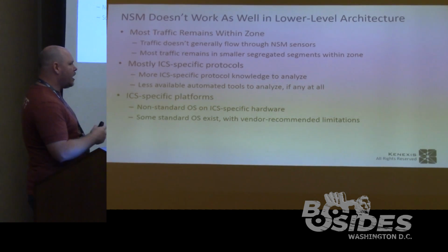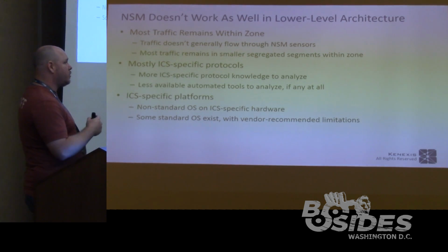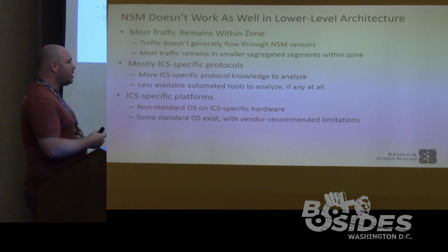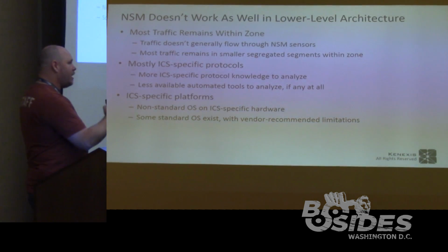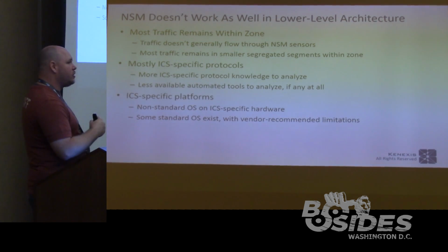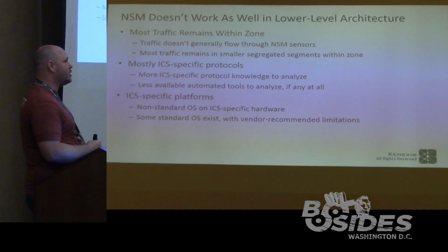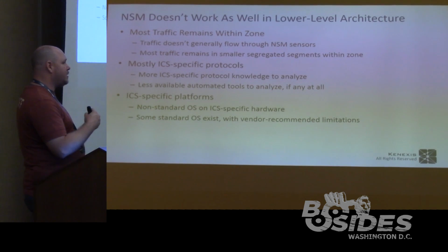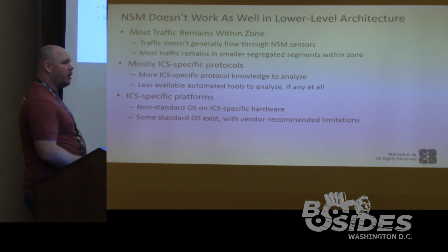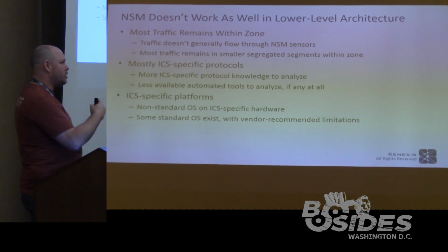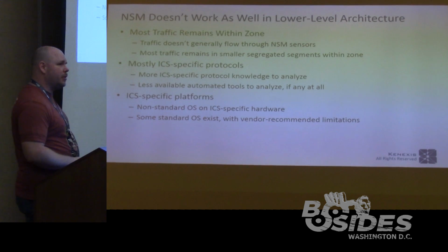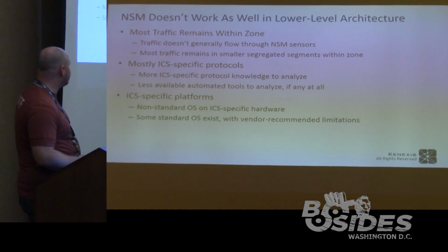Again, you're not dealing with standard OSs. A lot of times these are real-time OSs. If you've heard of VxWorks, that's a high-end one used in a lot of systems. A lot of these guys decide to write their own real-time operating systems because they can get down to sub-microsecond timings and determinism, sometimes down into nanoseconds of jitter on their communications. So very low jitter on their systems.